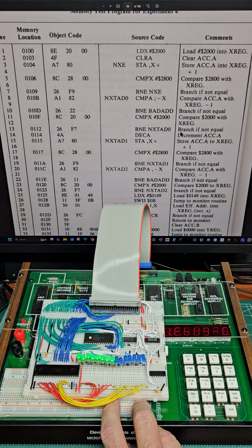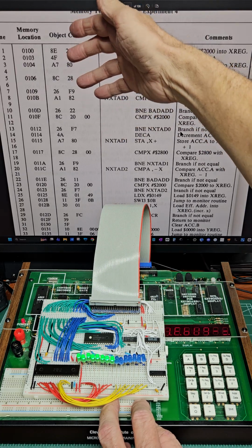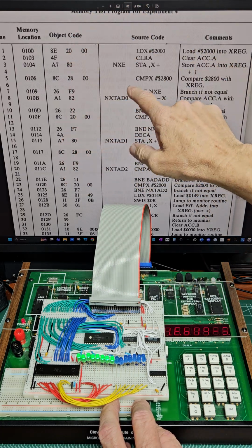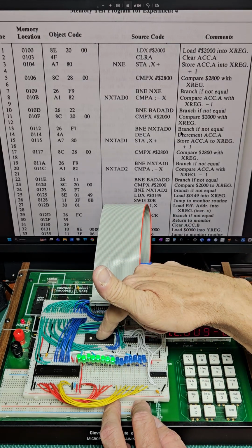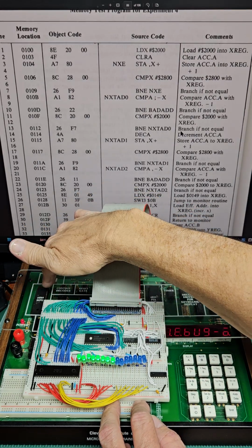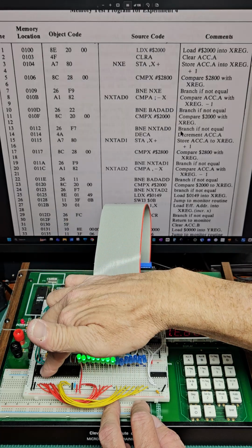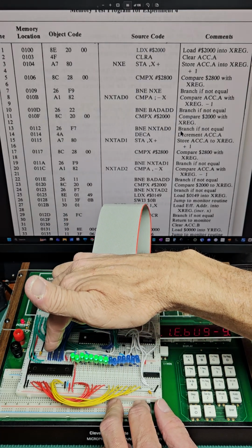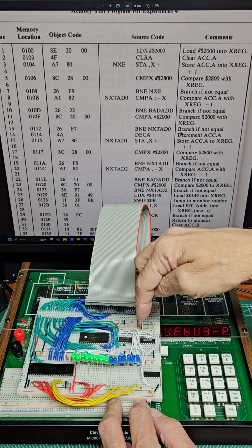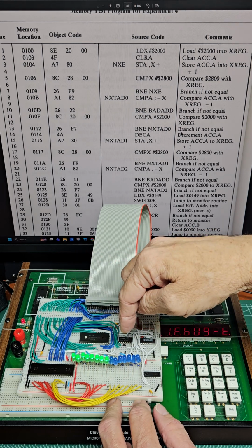And that's just to make sure that things are working right. And then I wrote a program, not this one, it's a different program I put in, and wrote it onto the ROM itself. And what this program does, it tells the processor to control the PIA. And it tells it to make all the pins output pins. So no input, they're all output pins.